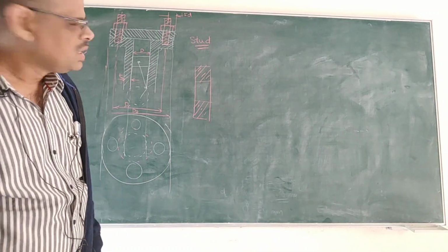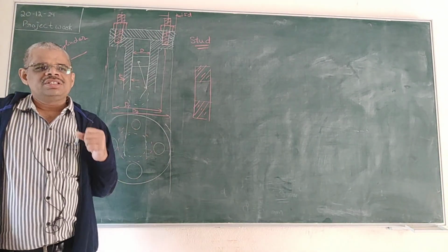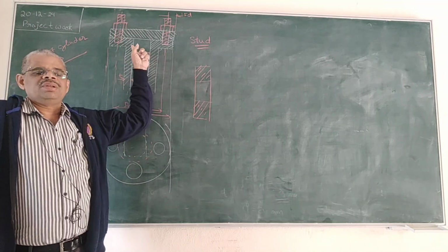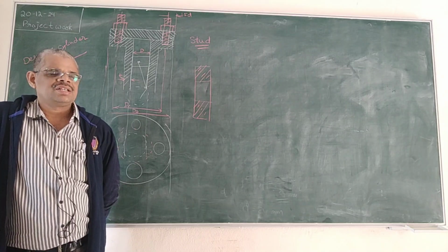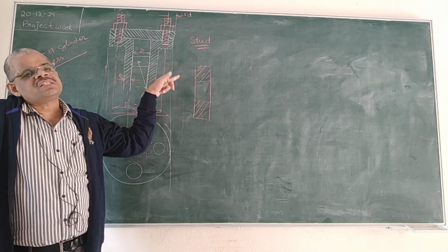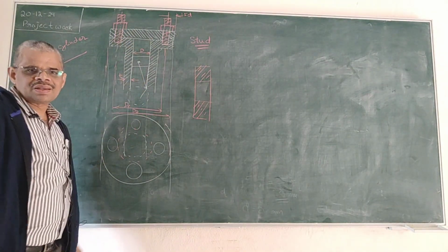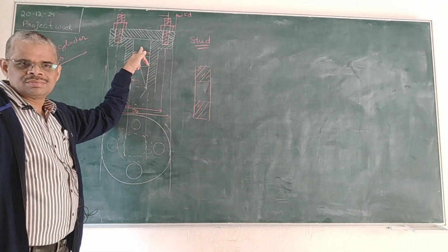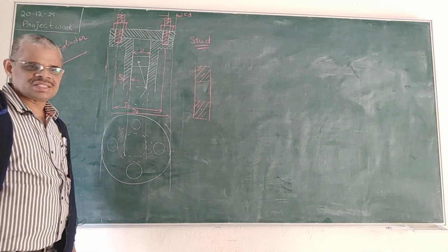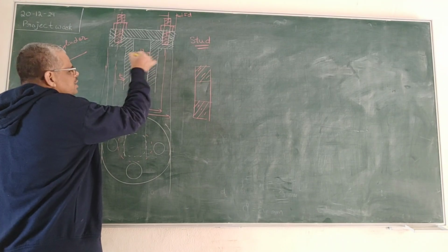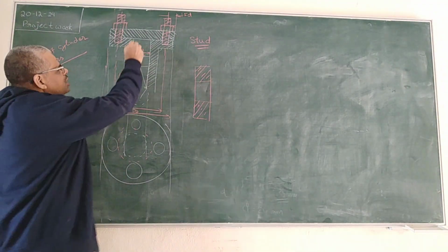made. Now, let us discuss what are the possible stresses that may be developed in these studs. So, before going to discuss about the stresses, let us see what are the different forces acting on the studs. See, what happens inside the engine? Tell me. What happens inside the engine? Combustion takes place, so that the flue gases, the combustion gases, will exert force on the piston. Is it right or not? It not only exert force on the piston but also on the head also.